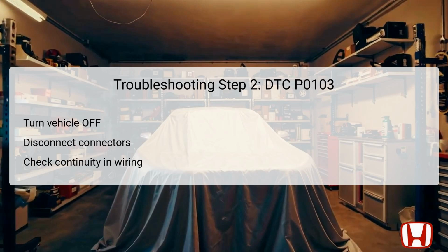Moving to the second troubleshooting step, turn the vehicle to the off-lock mode. Using the Honda Diagnostic System, HDS, you need to jump the Service Check Socket (SCS) line, then wait for more than 1 minute. Following this setup, disconnect the MAF sensor IAT sensor 5-pin connector and the PCM connector A, which has 51 pins.